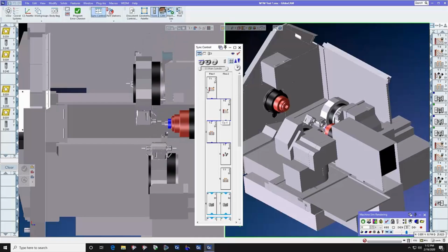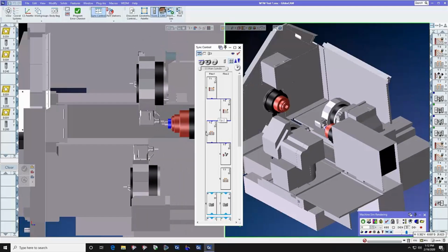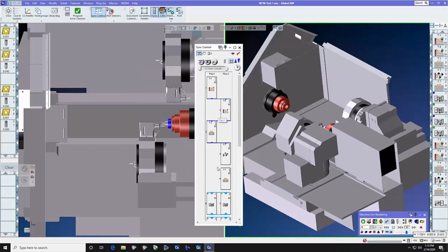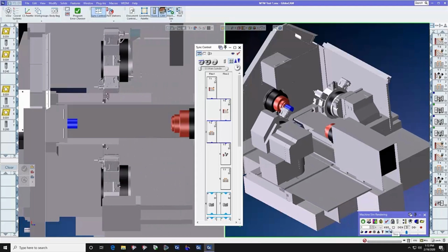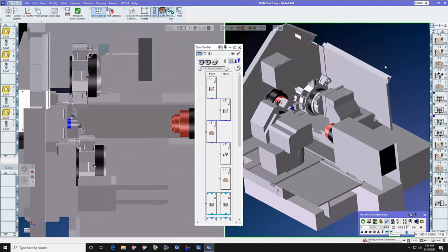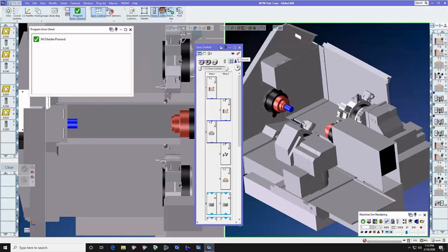This would be operation 1, operation 2, operation 3, 4, 5, 6, and 7. And we have the ability to coordinate those operations together. We have a sync here at the beginning of the program that tells op2 to wait until op1 is done. We're going to ruin that, and we're going to use the program checker to tell us if everything is okay or not. I'm going to ruin it by removing the synchronization between ops 1 and 2.